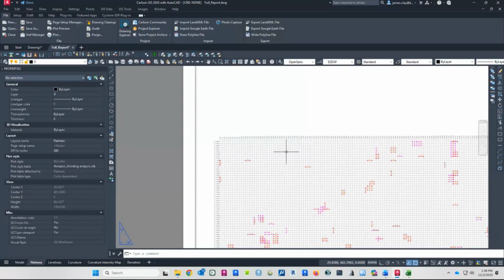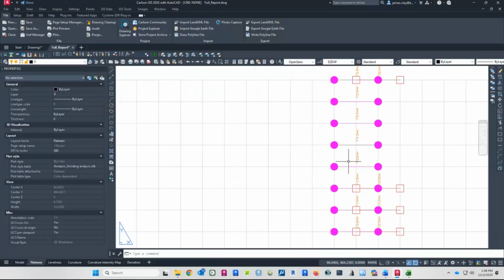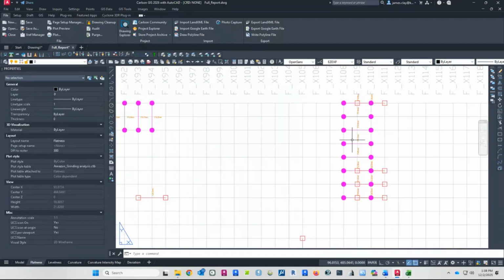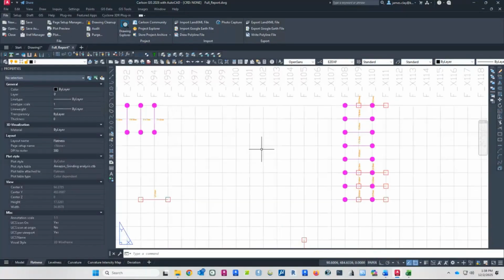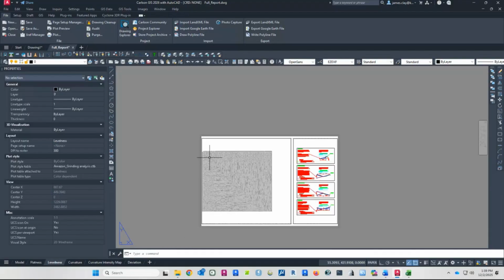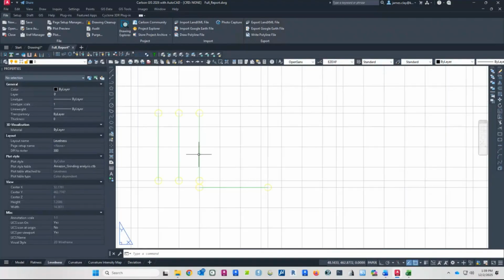And across the floor, you'll see all these failures. There are floor flatness, concave and convex failures. And these will be concave. So they're saying fill 0.6 millimeters to get back to specifications. And of course, if you wanted to, it's easy enough to turn on the contours on this model space also and deliver those. A lot of times we'll have those on when we deliver each one of these different model spaces, so that the remediation team can understand better just what they're looking at with the cut and fills, and also why it's doing that, what the floor is doing.